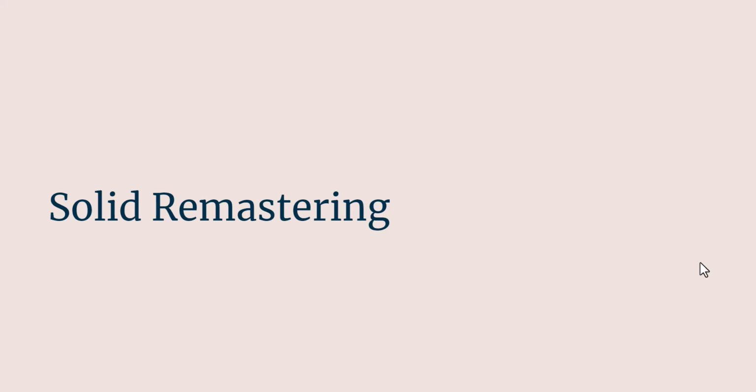We will be using the multiple body concepts as well. We may use Boolean operation in that. Also, we will be using the measure toolbar. So I would recommend you, before going on to the remastering, just go through the sessions that we have covered on the Part Design workbench. These features we have already covered in that. Now let's move on to the solid remastering.